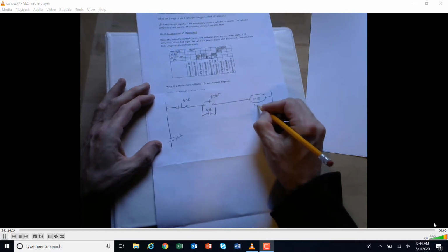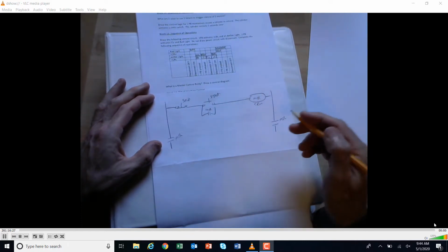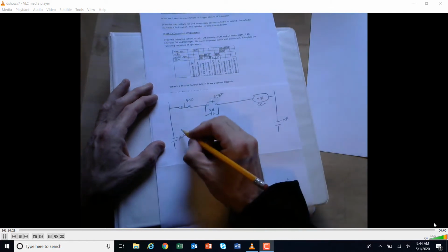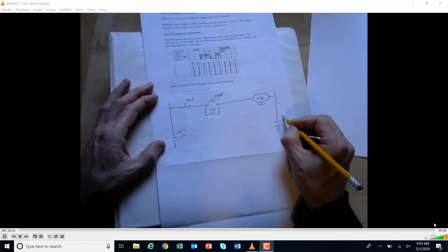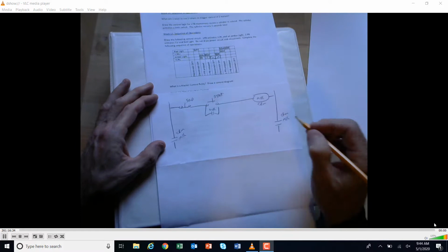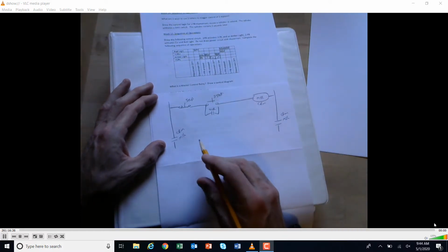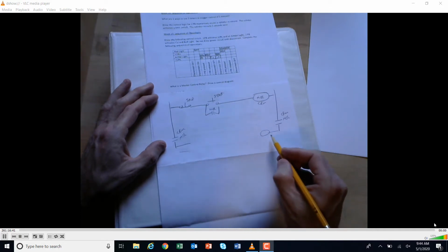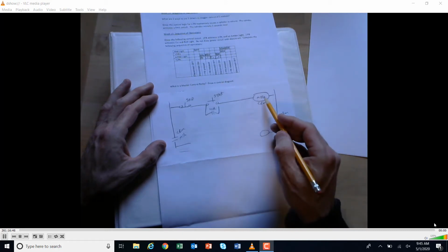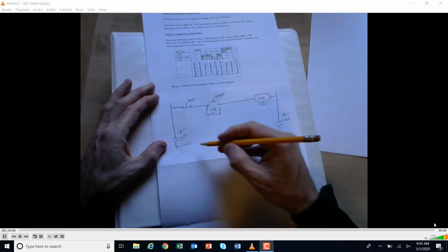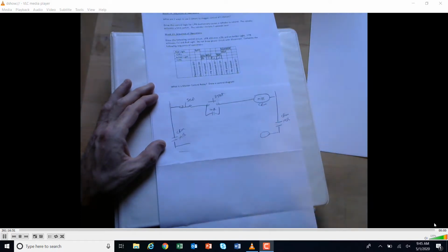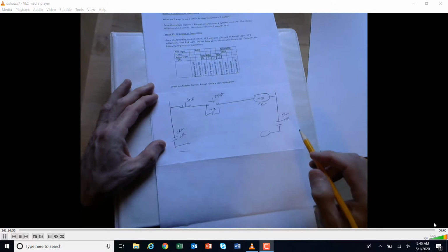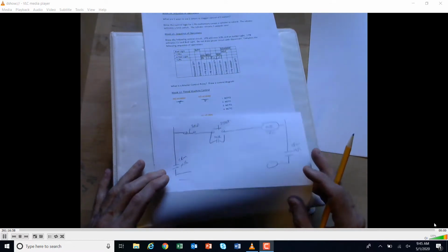This is MCR. This is probably better known in solid ladder logic as CRM. So maybe this would be control relay master, CRM. Either one of those is a designation for those coils. At which point any ladder logic that we have down here, these lines, are now activated because these are closed right here. But unless you turn on the master control relay or the CRM, these are open, and all the ladder down here is not going to be energized, so you won't be able to do anything. So that's how a master control relay works.